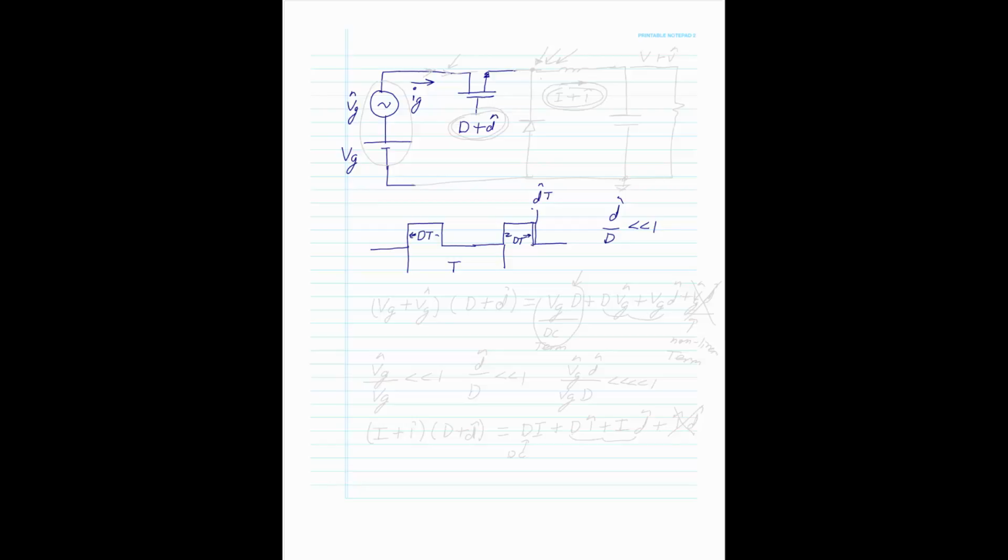You're just doing a small signal perturbation so that you can determine your loop gain, because the loop gain is the small signal analysis. Any large signal analysis like pulse transients, loop gain is gone. You don't even consider loop gain because any large signal is going to saturate the op amp, and in a saturated loop, there's no loop. So this is all small signal.